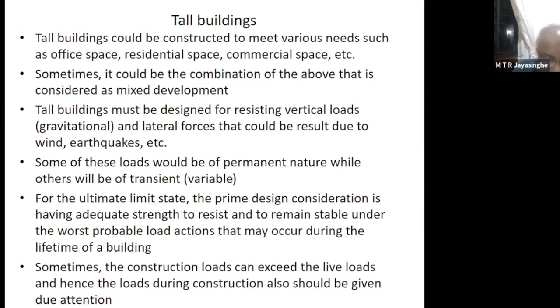The moment you have fly ash, the byproduct of the hydration process, calcium hydroxide, will start reacting with fly ash, and what is the end result? You are going to get a higher strength concrete, and a concrete that is capable of gaining strength over a longer period of time. Even after 90 days, you will find the strength is still increasing slightly. So which is a better concrete?